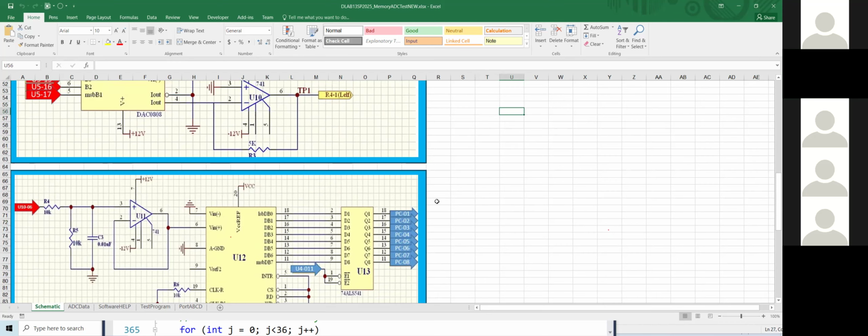And now, pin number 6, they connect to R4 here. R4, R5, 10K, 10K, that means voltage divider. If you get 10 at pin 6, at this point here they will be half, 5 volt.